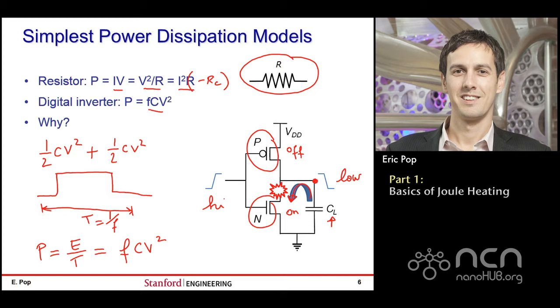This is actually quite important as well, and also a very, very basic and obviously easy to derive power dissipation formula, because it reminds us that in digital circuits, frequency, parasitic capacitance, and voltage are by far the most important components. This, by the way, also explains why the frequency in recent digital circuits has plateaued at about 2 to 3 gigahertz for many, many years now.